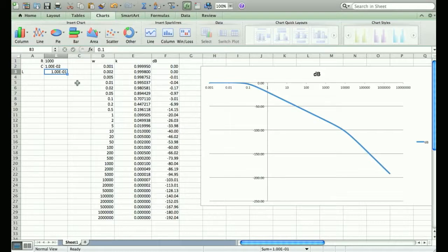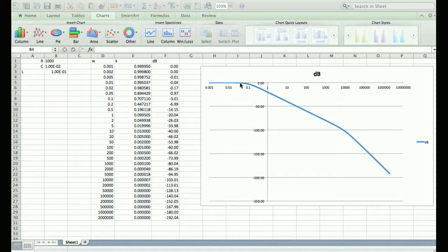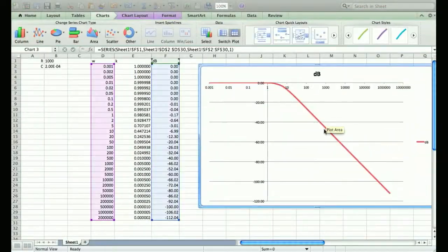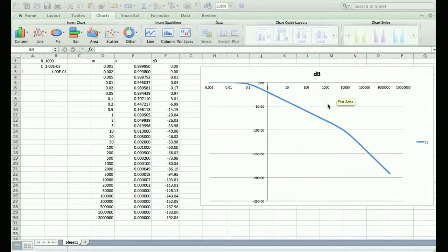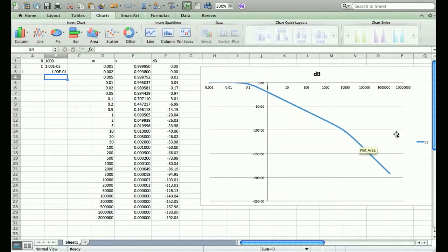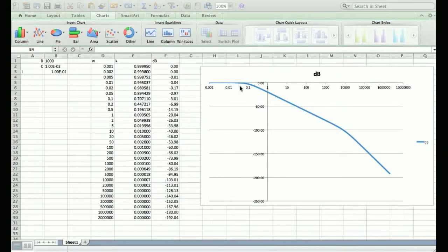Why do we see this? You guys kind of see how there's like a kink? It appears to be following the slope of the RC circuit here, but then it drops off faster here. Do you have any idea why that is? Given our values, R is 1 kilo ohm, C is 10 microfarads, and I believe L is 10 millihenries.